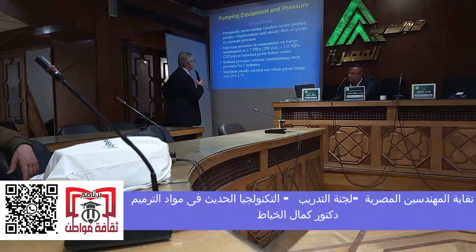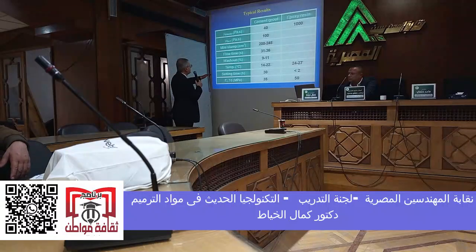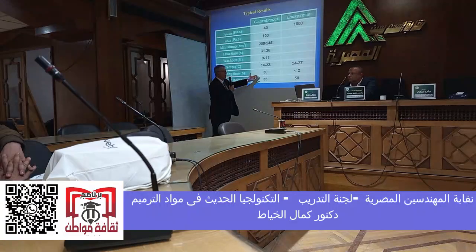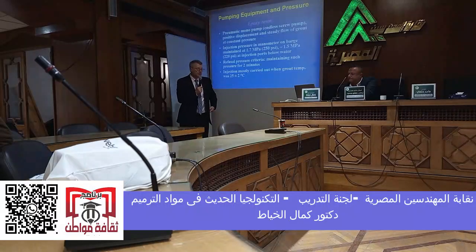Okay. No, please go back. Okay, this is very important. So these are the properties of the cement paste. Again, it was microfine cement, epoxies. Setting time: it did not set for 30 hours. It's microfine cement, lots of slag. Doesn't bother us. It's important to set and harden as long as it's stable. Next.